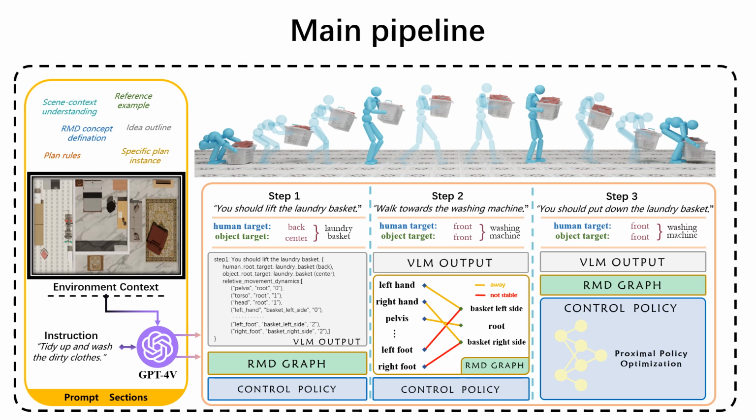The planner generates outputs structured as bipartite graphs, with nodes uniquely pairing human body parts to respective object parts. Each bipartite graph corresponds to a distinct temporal segment, within which the relative movement pattern between each paired human and object part remains consistent, before transitioning into subsequences. These planned subsequences are subsequently utilized as inputs to the control policy, which executes them sequentially.